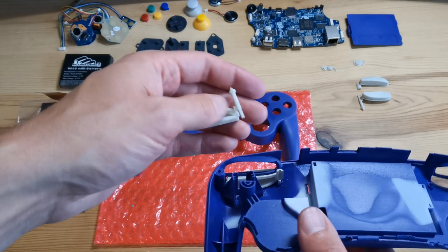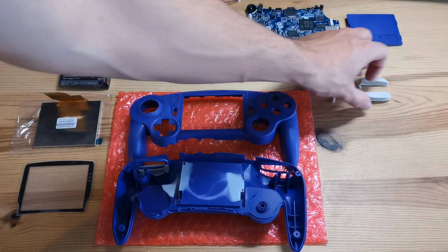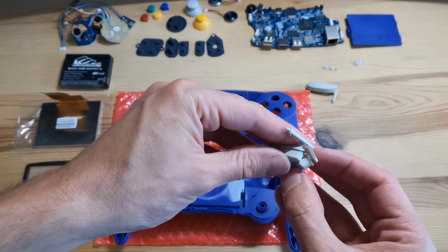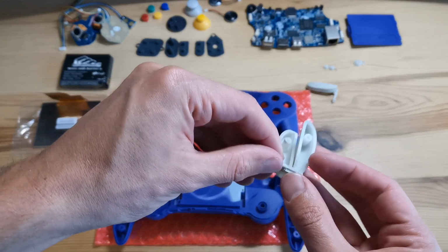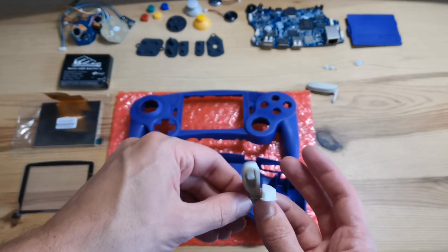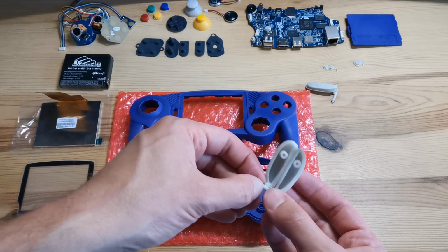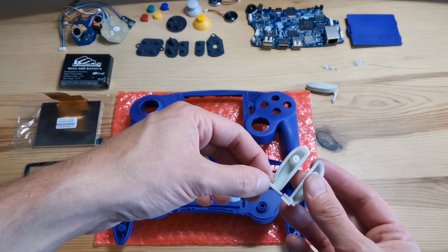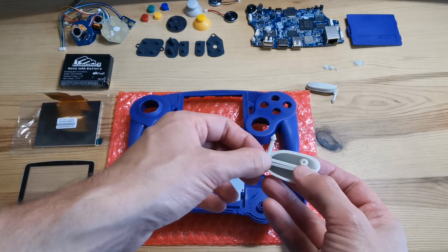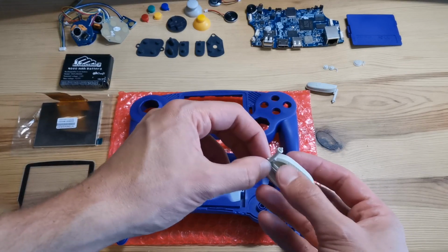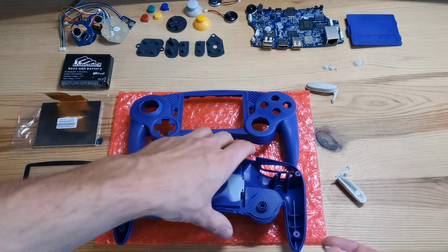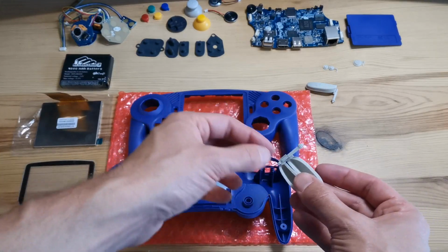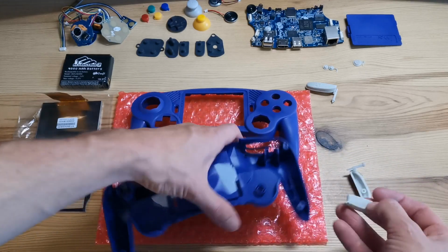But another thing that I will probably modify is the way those two buttons are designed. First, I made those two as separate parts, and the idea was that each of them should be able to move freely on the axis, because I don't want pushing one button to push the two buttons together. But this makes a rather complex design, and I fear that it may not last enough. So I will just try to make those two buttons only one part and see if they can click independently.